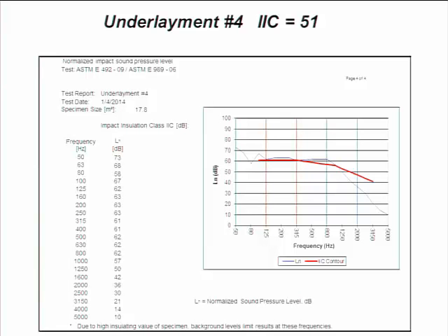But when you're looking at thin tile, another consideration is also that thin tile is rated for a floor installation. Many of the tiles are designed very thin in nature, but they're not designed for the floor. So there's some confusion in the industry in reference to where they can be used, and there needs to be clarification on the manufacturer as to the acceptability of that tile for a floor application.